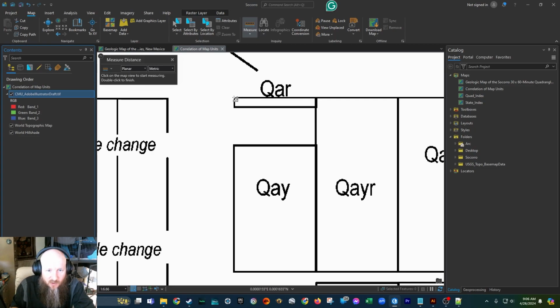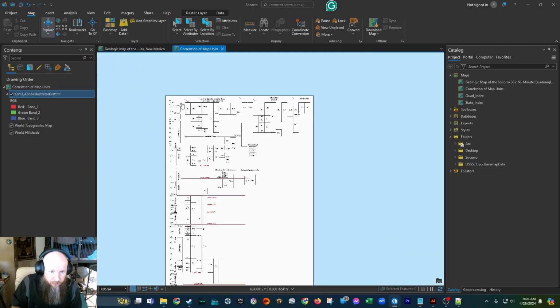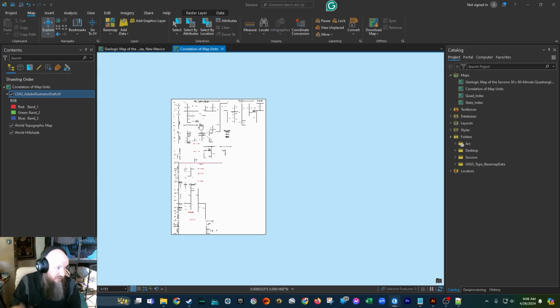Okay, so I'm going to then go ahead and measure this, and we can see that it comes in at 0.5 meters. So if we were to digitize this as it comes in, our scale is 1/2 meter instead of 1/2 inch. So this is the reason why we're trying to get this locked in in a more logical sense that really physically makes it a size and dimension. So we know then that this isn't at size, so we shouldn't go ahead and digitize this right from scratch. We should go ahead and make a box that is the dimensions that we specified, that 33,000 by 48,000,